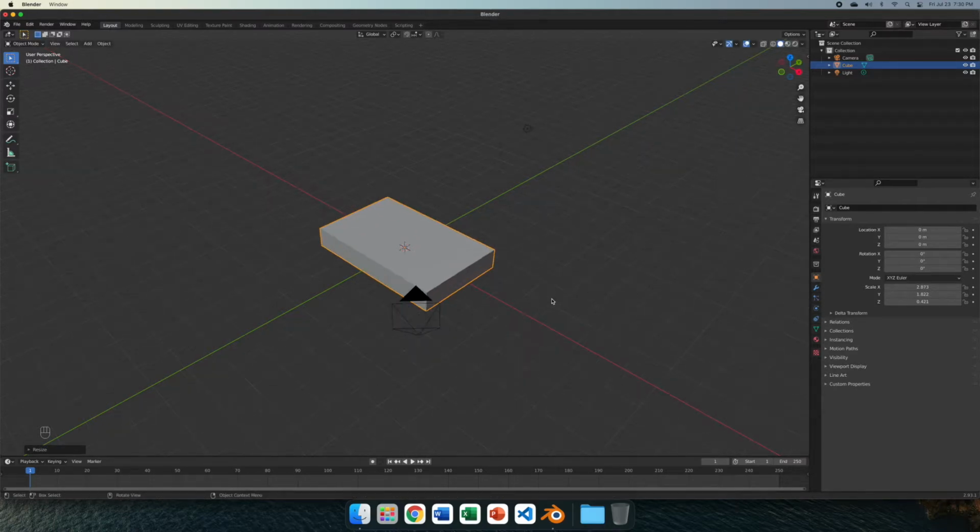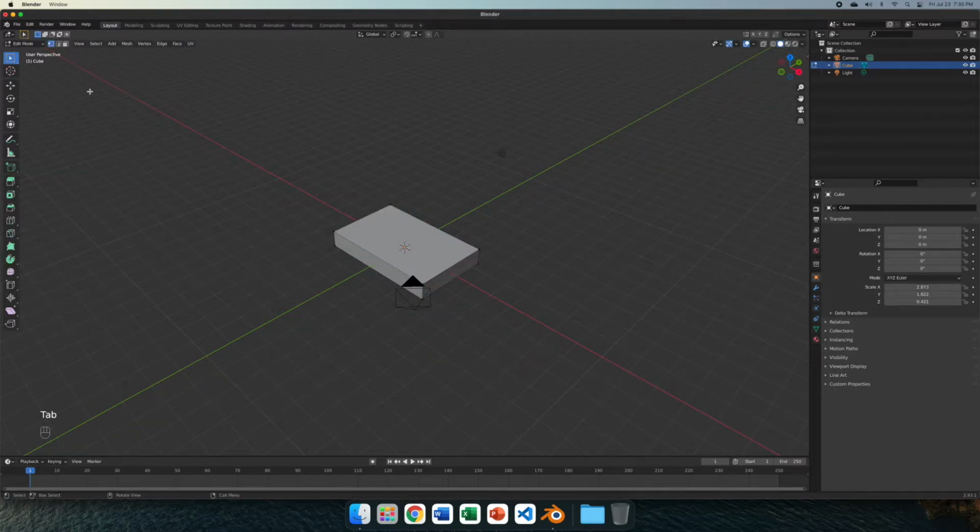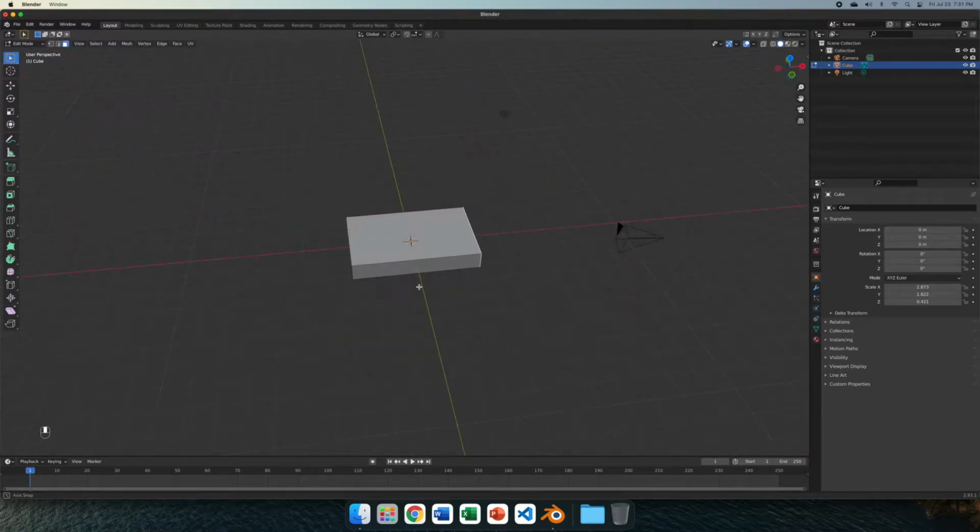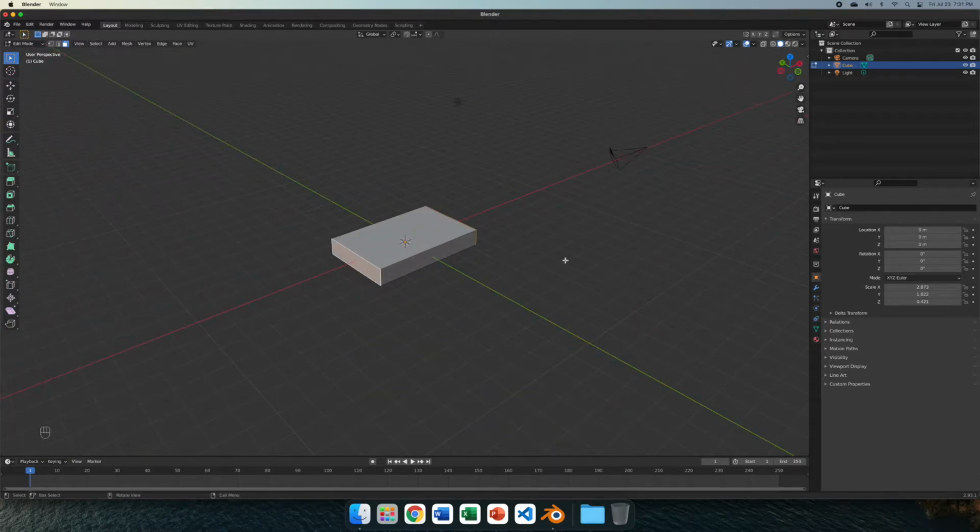And now we're gonna make the Joy-Cons for the Switch. So all we're gonna do is select the opposite faces on the X-axis, and then just press Option E to extrude faces along the normals, like so.